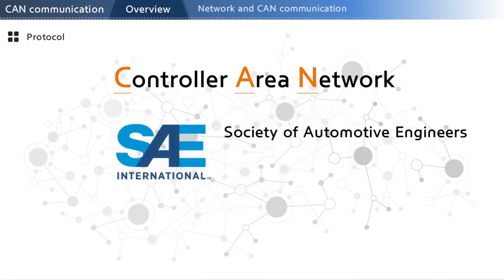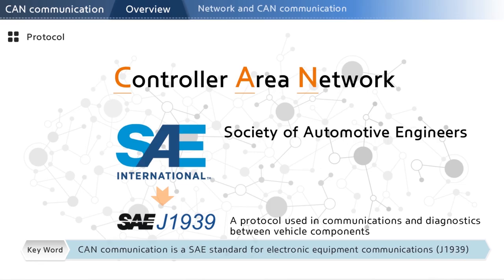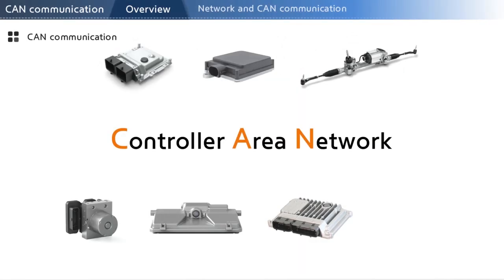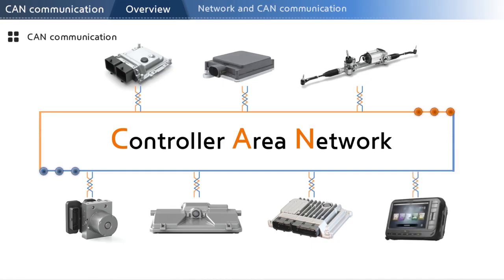The protocol is defined by the Society of Automotive Engineers standard SAE J1939. The configuration is quite simple. Controllers send their data to a network of two communication lines to share information. Connecting a diagnostic device to this network allows for accurate inspection and calibration of all connected controllers quickly.